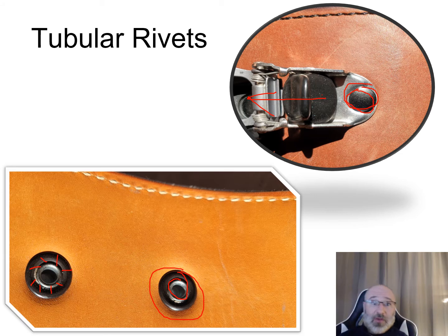Now, standard applications like this, a lot of people don't use rivets in this situation. Just like we talked about with the construction building, sometimes it doesn't make sense to use a rivet. A lot of people will go, for this case here, with a spider nut that they'll put on the bottom side there and a low profile truss head screw right here that threads down into that and threads into the spider nut that digs in with the prongs into the actual leather there.